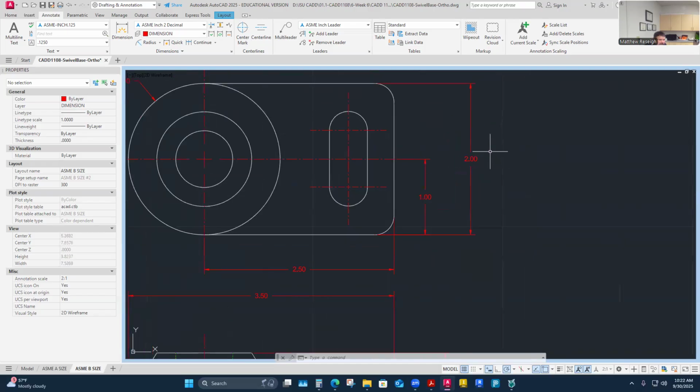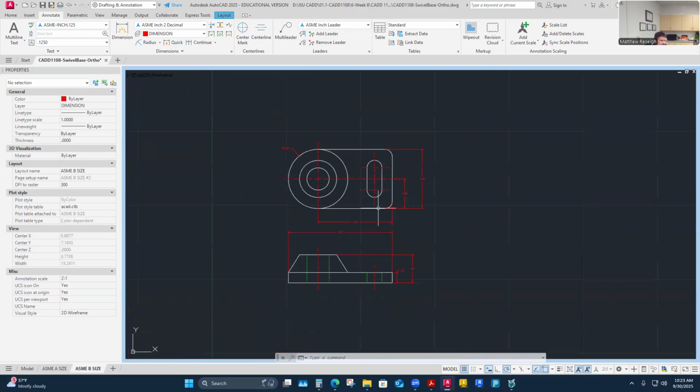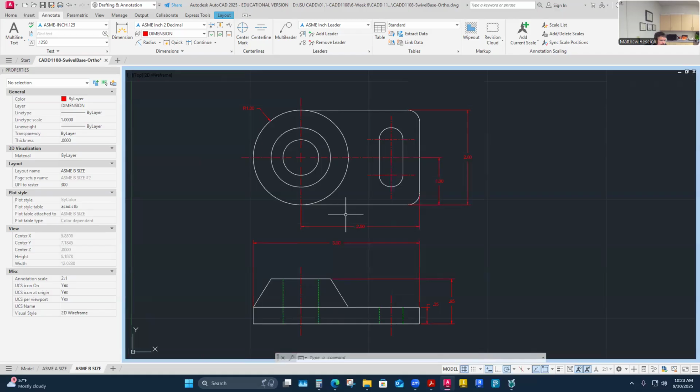And then if that was the case, how I would read these two dimensions together is this one is like from center line out, it's 1 inch. And then from there, it's like 2 inches. That would be like if I was mapping it out, like following a maze. This one's saying from center out. This one's saying from that over now 2 inches. Because the control would be here, center line, controlling this out 1 inch. And then from there, I'm coming back 2 inches. It's kind of this like little zigzag pattern. That's kind of how you'd read that if you establish this as a datum, which usually needs additional labeling and additional control to do that. And we're not there yet, but I'm going to keep pointing it out.